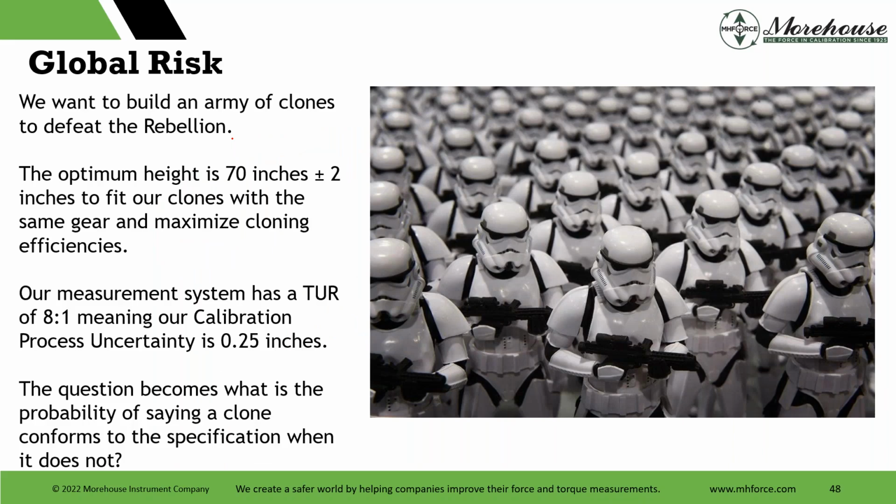Another Star Wars example. We want to build an army of clones. So this is global. This is where global really shines in manufacturing. The optimal height of our clones is 70 inches, plus or minus 2 inches, to fit our clones with the same gear and maximize cloning efficiencies. Our measurement system has a test uncertainty ratio, also measurement capability index, of 8.1, meaning our calibration process uncertainty is 0.25 inches. The question becomes, what is the probability of saying a clone conforms to the specification when it does not?